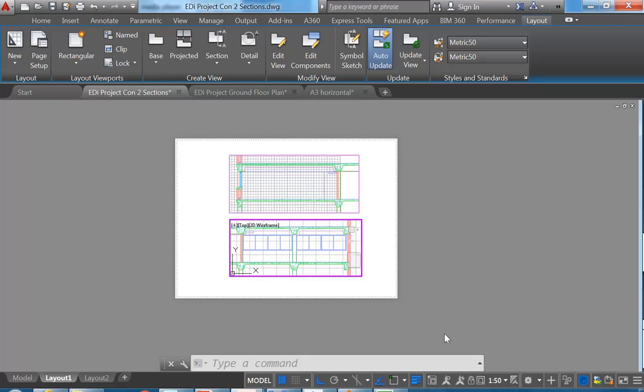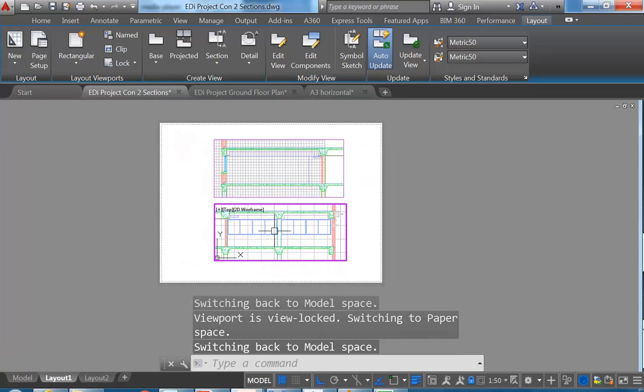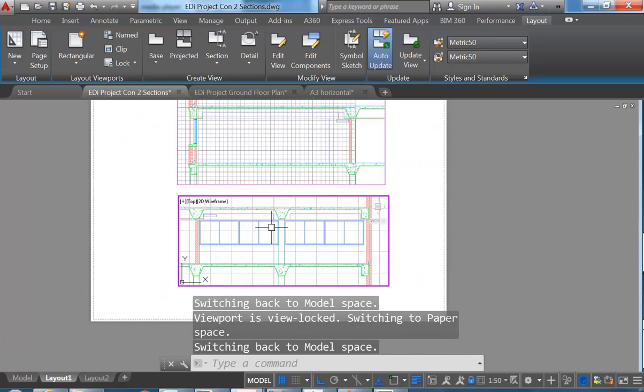So then, a really useful option, once you have set the scale and you've got the things showing in the viewport and you want them to stay that way, there's an option next to the scale that you might have seen before to lock the viewport display. That's a really, really useful option. Once you lock that display, you can't change the scale anymore. You can't even pan. If you pan, it's going to pan the whole page. And if you zoom, it'll zoom the whole page.